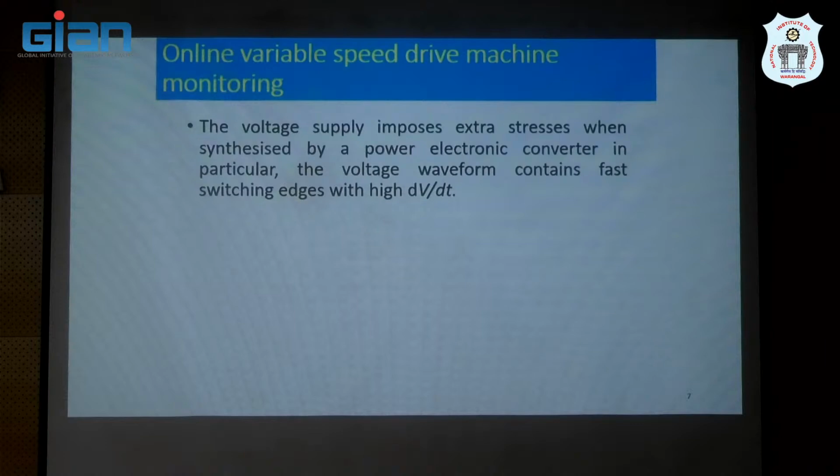we are going towards PWM switching using such devices. So these machines have to withstand both sinusoidal as well as repetitive impulse voltages. Also in the standards, partial discharge inception voltages are given for low voltage machines. Even endurance tests are to be conducted for medium voltage range machines also.